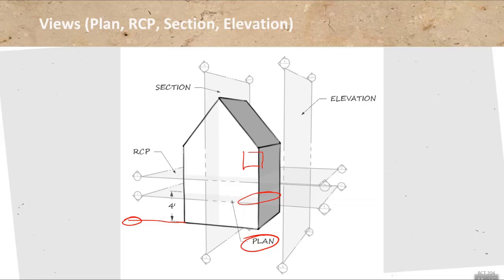We just talked about ceilings, and let's draw in a ceiling here. That needs to be represented too. You need to somehow make clear where the lights go and the HVAC outlets, etc. And that is done with a reflected ceiling plan, an RCP. Reflected ceiling plan basically means we're looking up, but it's done in a way that we're kind of taking the ceiling and we're reflecting it off the floor. And I'll show you in a second what that means.